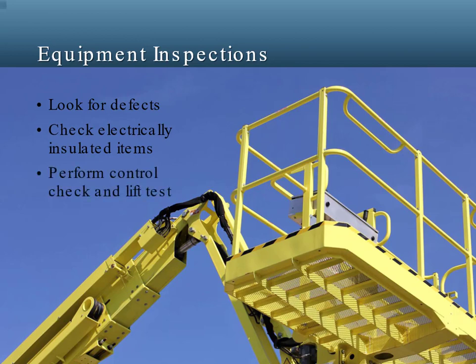Perform a control check to make sure operating controls are all functioning correctly, and perform an operating test on the lift itself. And finally, potentially unsafe items discovered through inspection must be carefully examined, and a determination must be made by a qualified service person as to whether the problem constitutes a safety hazard. All unsafe items and conditions must be corrected before the aerial lift can be used. Think about the inspection procedure you need to perform before using an aerial lift.